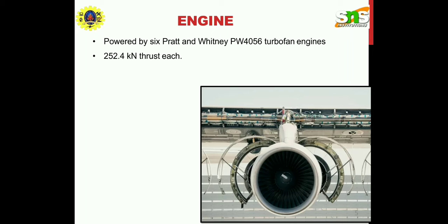So, radial flow turbo machines: when the path of the flow is wholly or mainly in a plane perpendicular to the rotation axis, the device is termed a radial flow turbo machine. Therefore, the change of radius between the entry and the exit is finite. The radial turbo machine can be inward or outward flow type depending on the purpose that needs to be served.